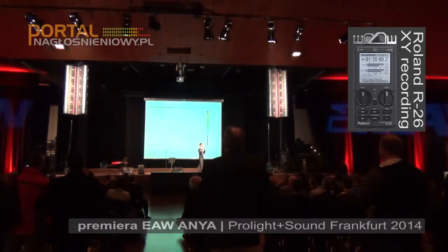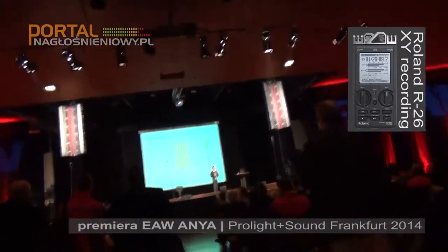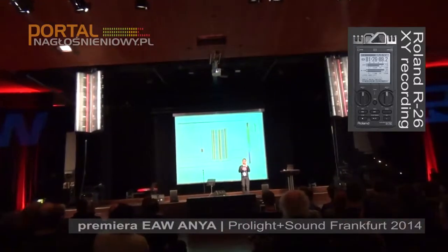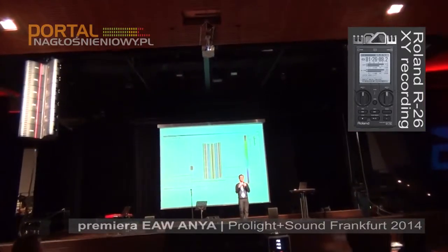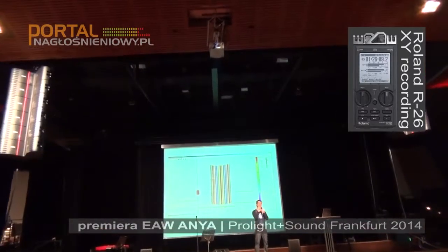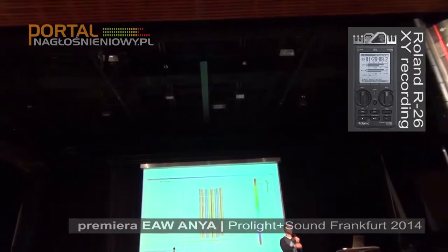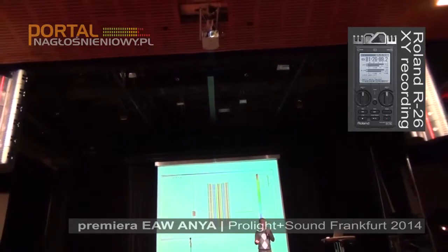But we would rely more heavily on the traditional physical aspects of the horizontal array system to cover the needs in the horizontal plane. But we didn't stop there. What we actually envisioned was several very long vertical ribbons of sound arrayed in a horizontal arc, each one of those ribbons with discrete control, and then actually within each one of those ribbons, additional discrete control of very small segments.